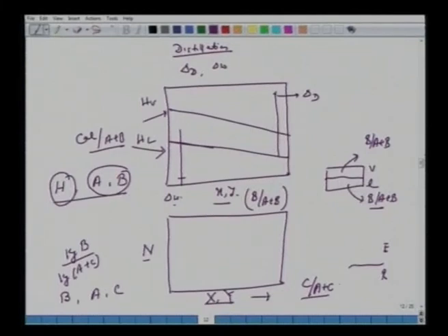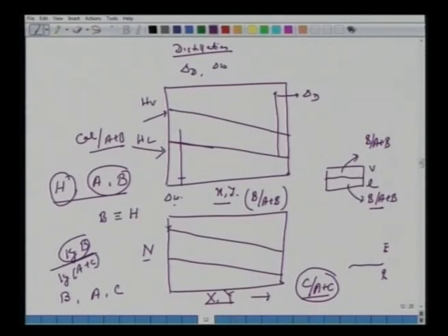Here we have vapor and liquid, here we have extract and the raffinate, two phases. Here we have X and Y, which is B over A plus B, here we have C over A plus C. So we have similar situations, and qualitatively one can show that you will have the same treatment. You will look for this del depending upon what the reflux ratios were in the case of extractions. From the reflux ratios, you can get this F connected here, and one can find again a tie line connecting with this, another tie line connecting with this, etc.